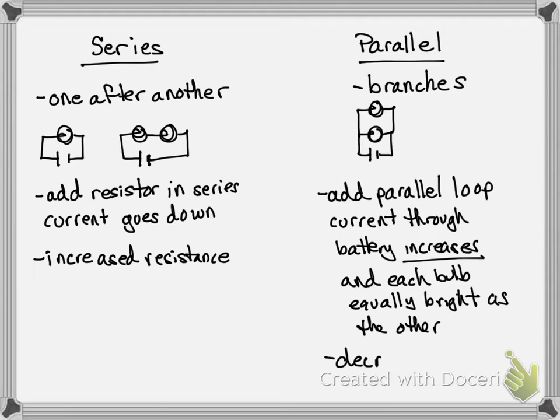And so that first bulb, the original route, has current flowing through it. And then when the last wire is connected for the top loop, it gets current flowing through it too. So what does that imply about the amount of current that's going through the battery? Well, it's the current that's been going through the first route the whole time. And in addition, also the current that is now going through the top route, because everybody has to go through the battery. All the current has to go through the battery.